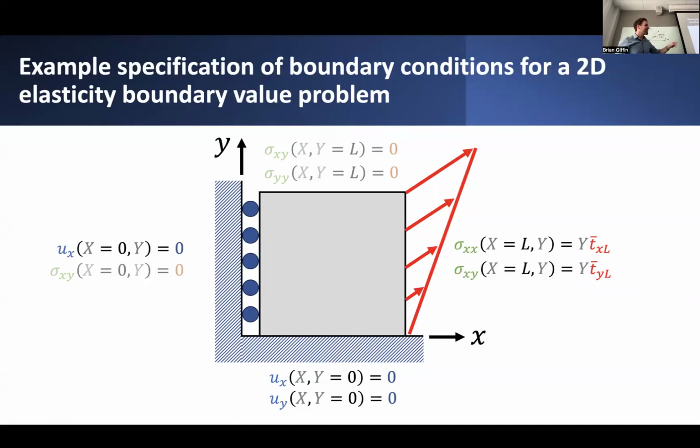So in that case, we can make it look like we only constrain ux, the component of displacement basically normal to that surface, but then just let it slide freely along that kind of vertical plane. And implicitly what we're doing is we're saying that we're not prescribing the displacement in the y direction.